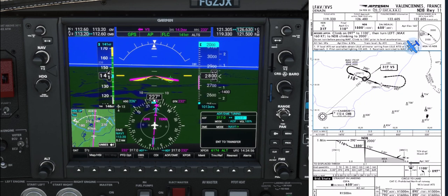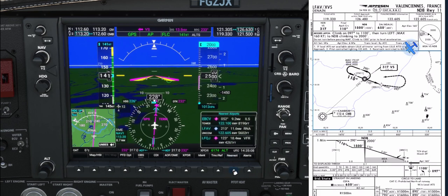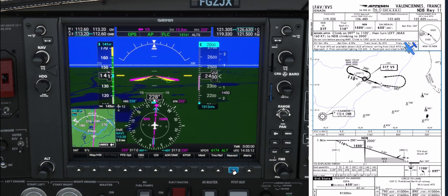Overhead Victor Sierra, apply the 5 Gs: gear, glide, go timer, go around altitude, green lights. Timer will be for 1 minute and 59 seconds to the missed approach point for a ground speed of 100 knots. Follow the descent path down to the minimas of 650 feet. We need an RVR of 1,500 meters.